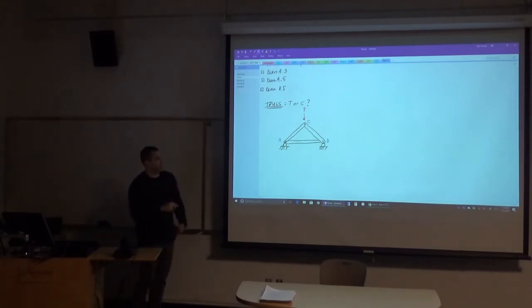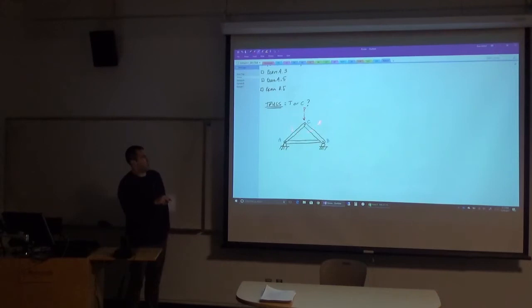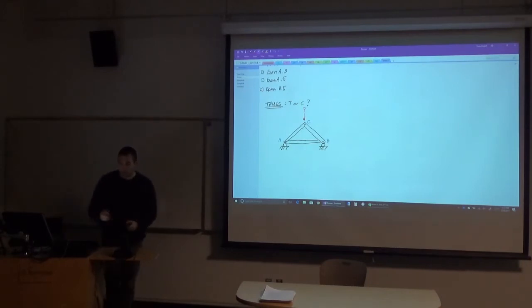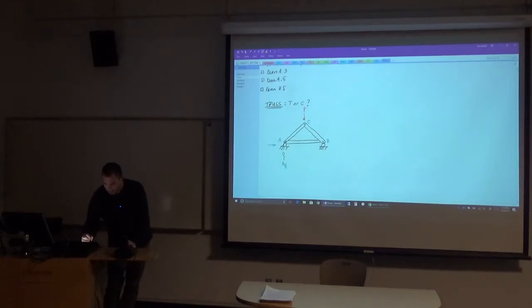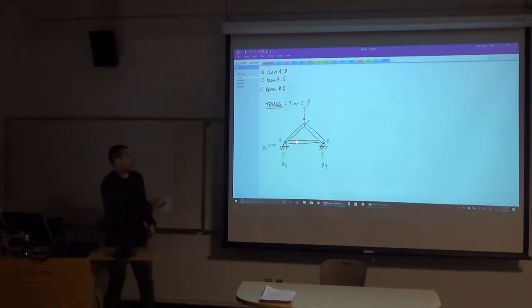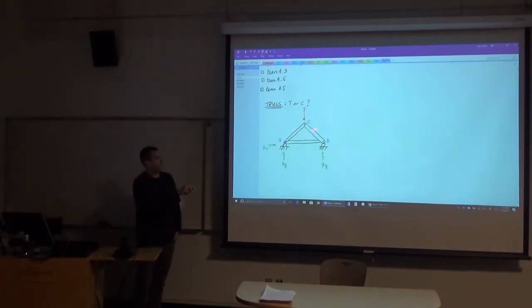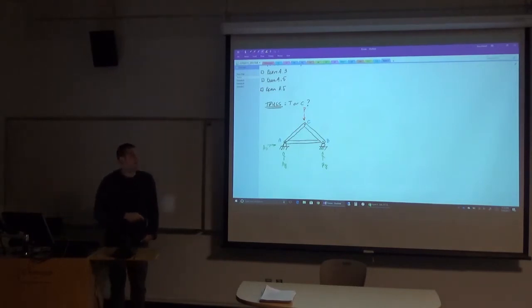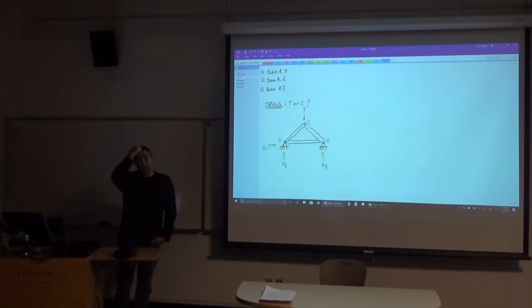And so the way that we would analyze a truss like this, I can start with method of joints right here at this section, or we could even do method of sections if we wanted to. I'm going to assume first that I've got these support reactions. We'll call it AY. We'll call it AX, and I'll call this roller reaction BY. But even if I didn't have those reactions, I could still at least start with the method of joints up here at joint C. And so what does method of joints allow me to do? Well, how many unknowns can I solve for at a given time with the method of joints? Well, I will get 3 equations of equilibrium, but one of them is going to be trivial.